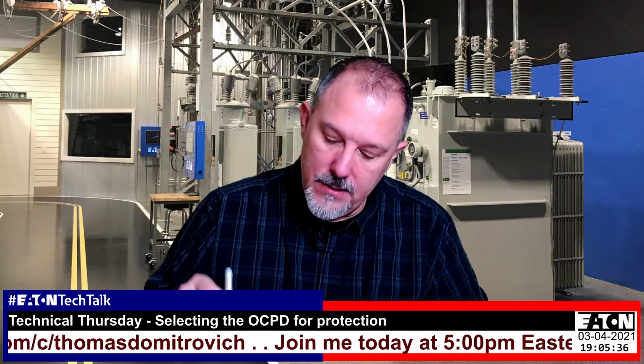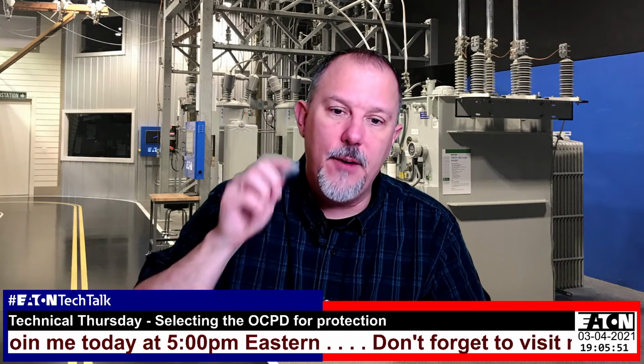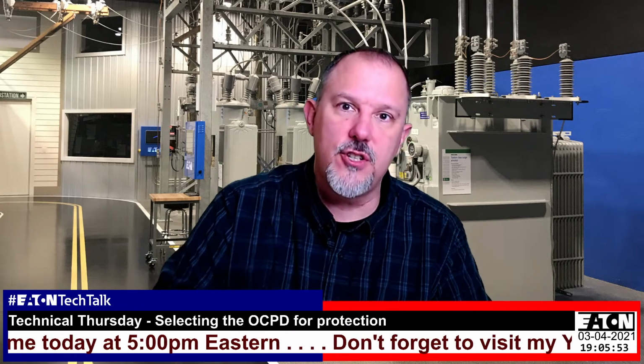So, in my opinion, we've got to look at 230.95, and we need to say that's about equipment protection of service entrance equipment. We need to think about moving that main overcurrent protective device, that service overcurrent protective device, into its own enclosure, and we need to think about looking downstream. So that's where my head's at now.